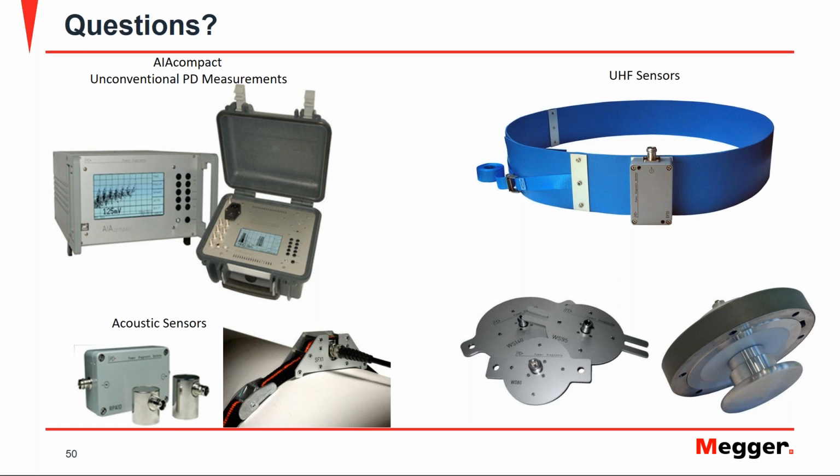The typical approach is that you start with an electrical measurement. The reason for that is that the electrical measurement is more reliable than the acoustic measurement because it is less easily disturbed. Accordingly, performing an electrical measurement will give you the indication if you have a PD source within your GIS. And only if the electrical measurement tells you there is something, then you apply the acoustic measurement to pinpoint down where it actually is within your GIS.